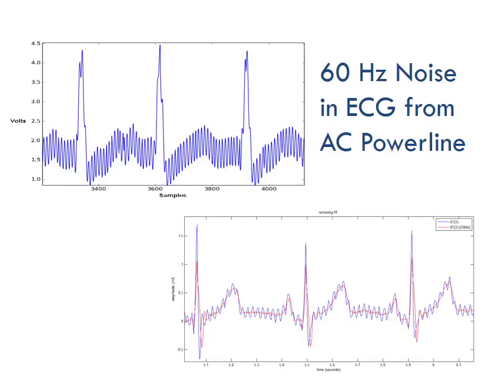In the bottom here, in blue, we have that natural signal from the top. In red, we have removed, either with a difference amplifier or a filter, the frequency that is the 60 hertz noise. The big point from this is essentially that frequencies can add and subtract. So you can remove some frequencies, especially if they're constant, like 60 hertz is a very constant frequency. We can remove that out of a set of data, and we're going to show you how to do that.